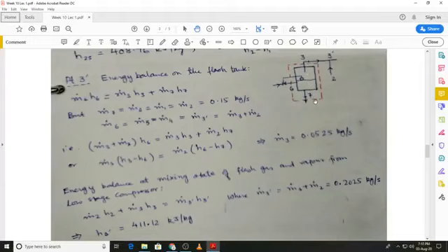But we know that m dot 7 is the same as m dot 8 is equal to m dot 1, because the same mass flow rate, that is the liquid refrigerant, goes into the evaporator and it reaches state 1 after passing through the evaporator, and this value is given to us, and that is also equal to m dot 2. M dot 6 on the other hand is the same as m dot 5 and that is equal to m dot 4.